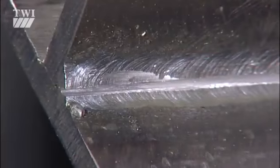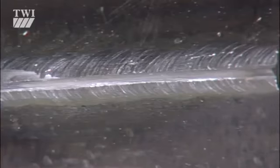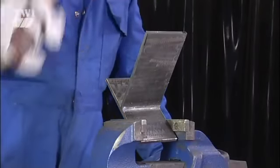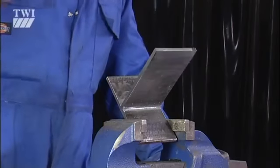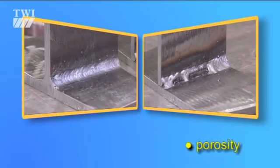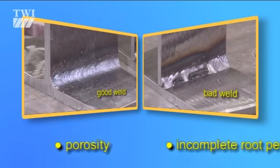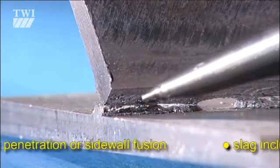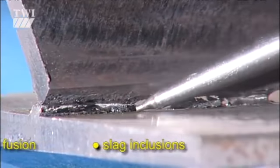Force is then applied to the specimen to bend open the weld using a testing machine, a press, or blows from a hammer. The fractured surfaces can then be examined for internal defects such as porosity, incomplete root penetration or sidewall fusion, and slag inclusions.